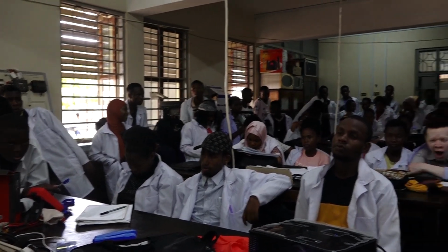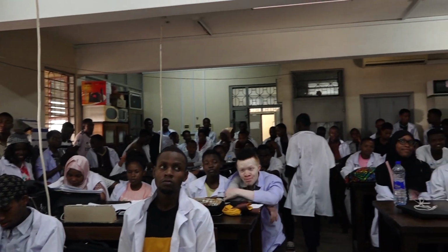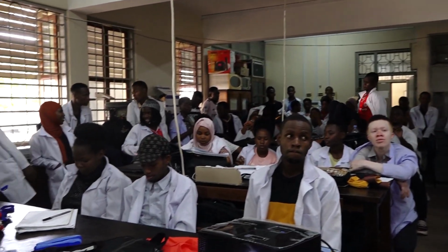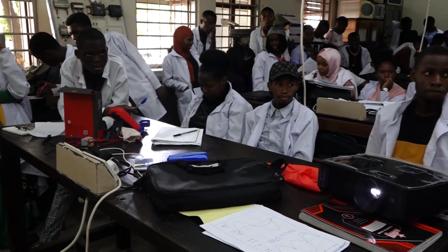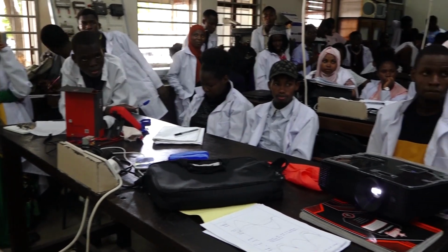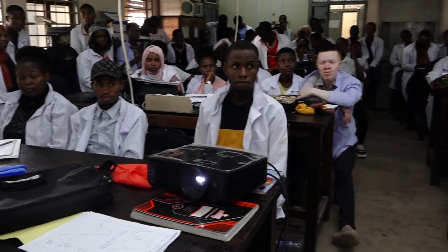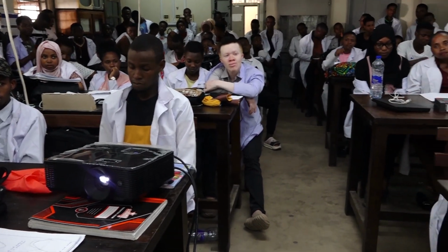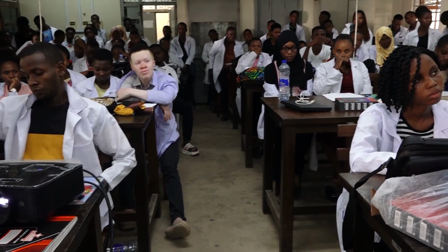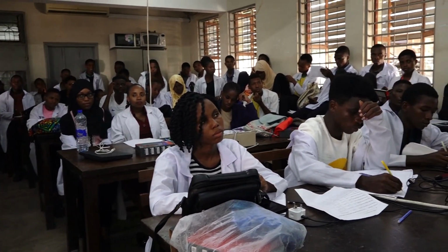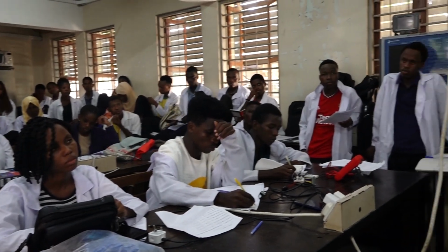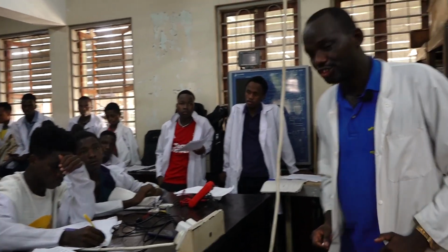Okay. So from today onwards, you have to know that the AC voltmeter gives you the root mean square voltage. The digital oscilloscope gives you the maximum voltage. If you fail to differentiate, you are going to get confused and panic, and you will hate the subject of measurement. Also, be a political, electronics and telecommunication what? Engineer.